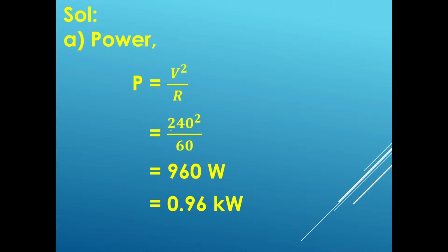It is 240. So 240 square by R, which is 60. So 240 square by 60, you will get 960 watts. Sorry, I said 940 earlier, it's 960 watts.